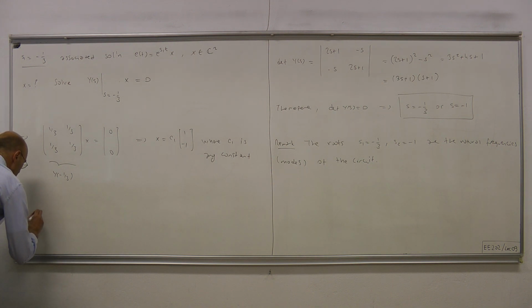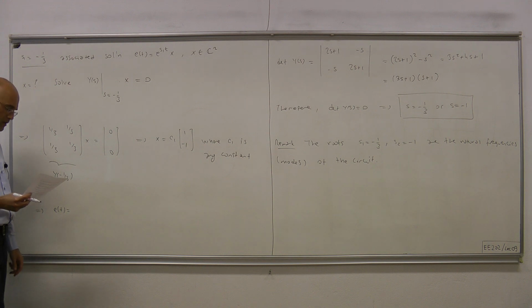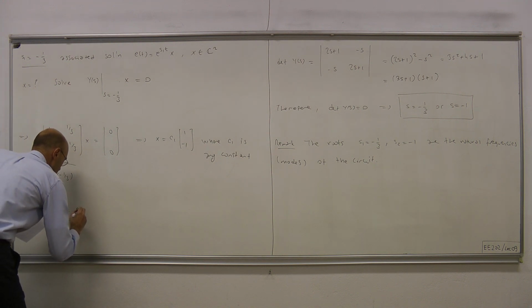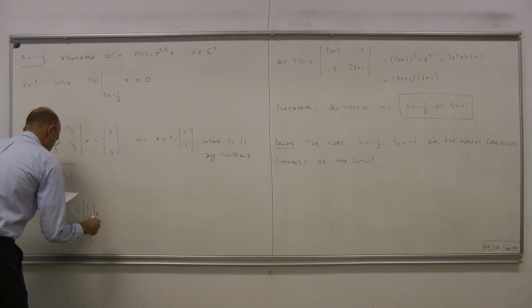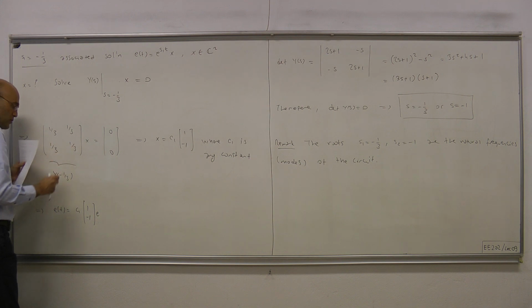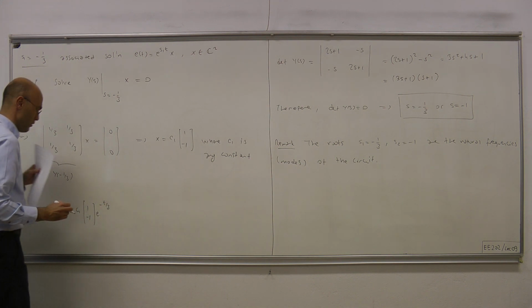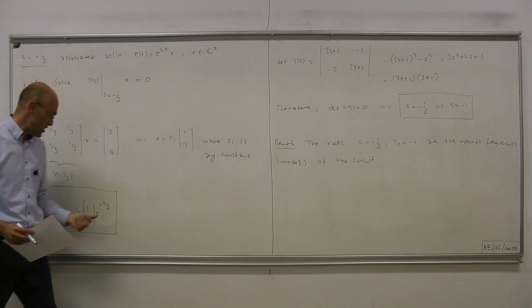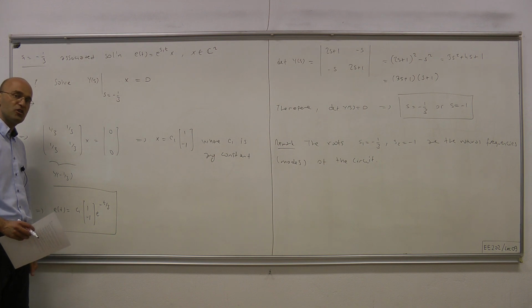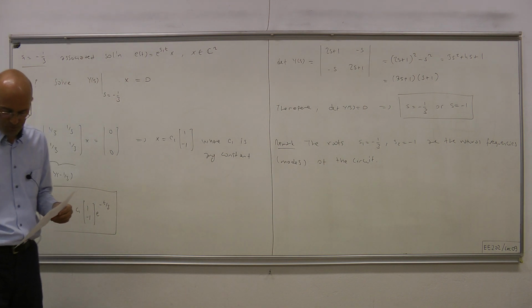Okay, so let's write finally the node voltage. E of t must equal some constant times this vector, which belongs to the null space of this matrix, times e to the minus t over 3. So, for any C1, this node voltage vector will satisfy the node equation. So that's what we will obtain.